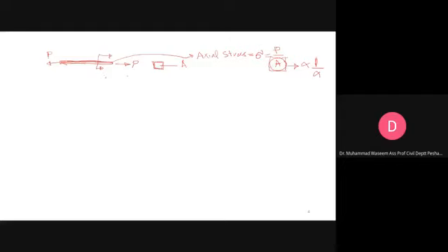When we apply the load, it will produce some stress in the member, and obviously it will also produce some strain. When we look at the stress-strain curve of a tension member, initially it will be elastic, then it will harden, then we will have some strain hardening, and then some degradation in the strength.